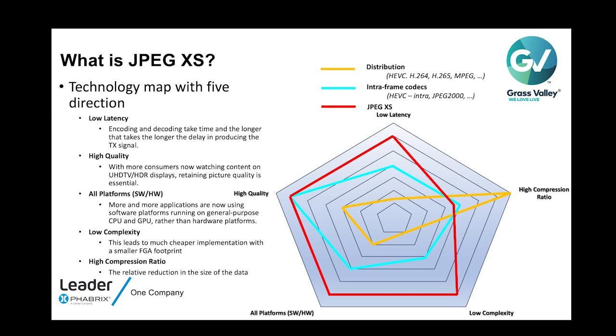Yeah, and well, within a normal large scale remote production, almost like what's behind you, JPEG XS sitting in a 2110 is gorgeous because it can intermix with uncompressed 2110 because of the absolutely low latency. And you could have feeds coming in maybe from the opposite side of the stadium and bring those over with JPEG XS and get a lot more cameras on the pipe that you happen to have from one side of the stadium to the other.